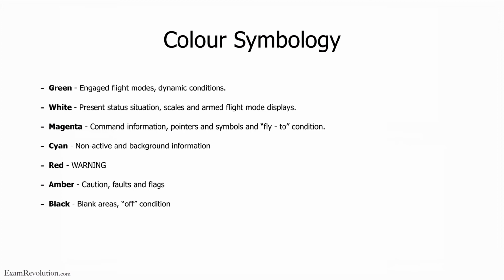So these are modes that you've selected on the autopilot or on the flight director that is busy running in the background. Like for instance, let's say you're busy intercepting a VOR. Now you've set the aircraft on a specific heading and you're going to intercept the VOR. Okay, then you're going to use nav function on the autopilot to intercept it. You don't have to know about all these things, I'm just mentioning it.